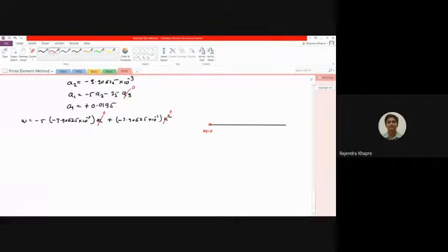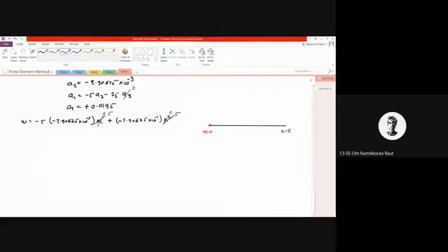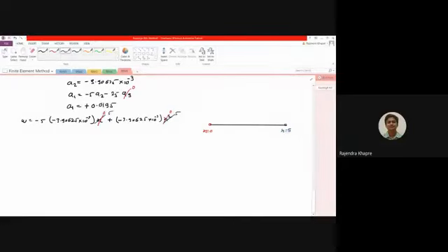Now if you substitute here the value of x as L, where L value is basically your 5, so say this x value is 5 now. Can somebody do the calculation, and what is the value of W with the x value as 5? Sir, 0 is coming? It should come, you haven't calculated. It should become 0 because here there is a support, so there should be a 0 value over here.